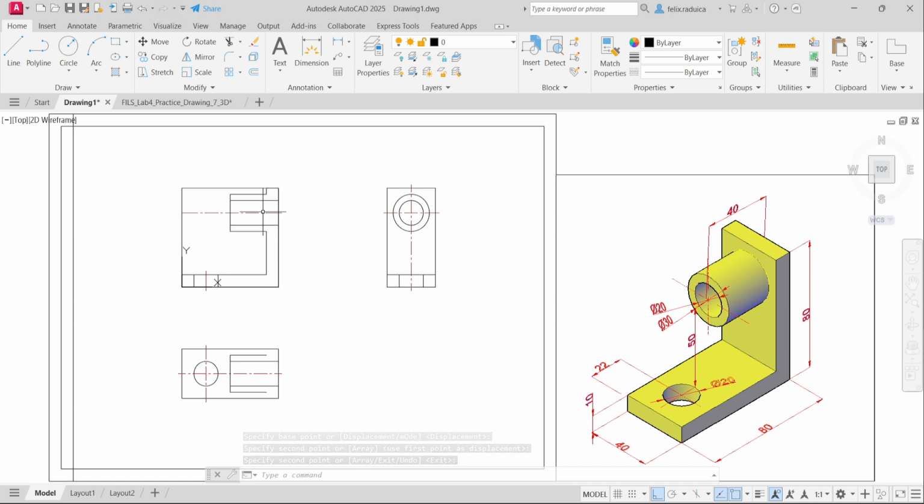We also need this line, so I can create a line here, or I can extend this one. So let's extend that one, extend it a bit, so we have the line there. And again till the end. Okay, tap enter, trim it, trim this and this, enter.